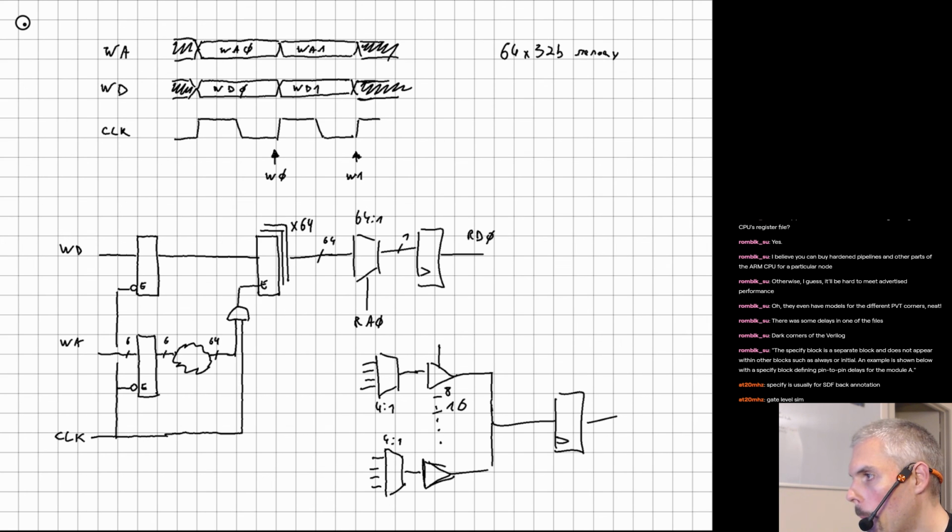It means that this cell is relatively large, and I don't want to have to put 64 of those. So looking at the area of the various cells and the difficulty of routing, putting a 4 to 1 mux followed by one of these, I think it's a decent compromise.